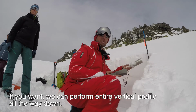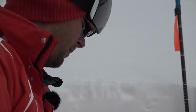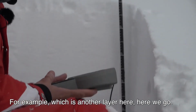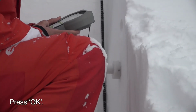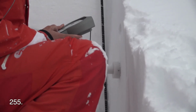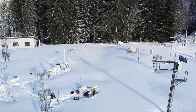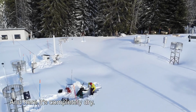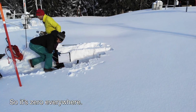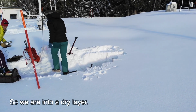If we want, we can perform an entire vertical profile, perform measurement into the snowpack all the way down. And for example, we choose another layer here. Here we go. Press OK. The density 255. And here it's completely dry, so it's 0 everywhere. Liquid water content volume 0, liquid water content mass 0, right? So we are into a dry layer.